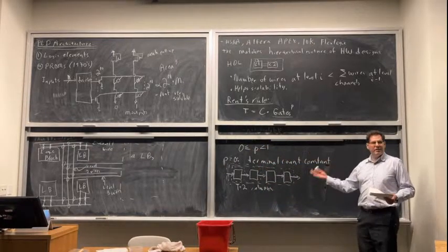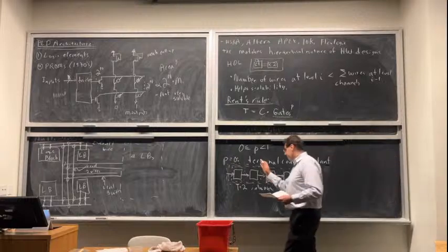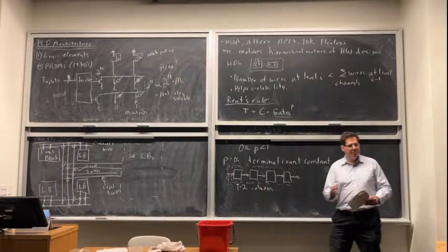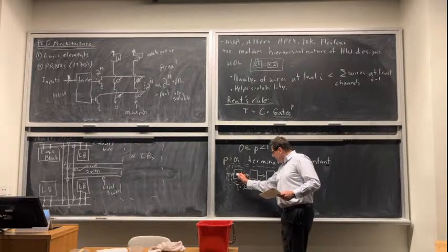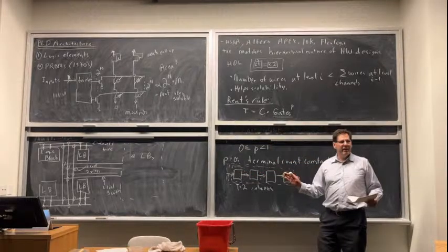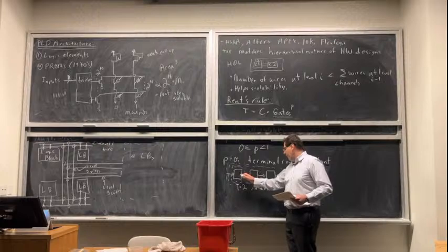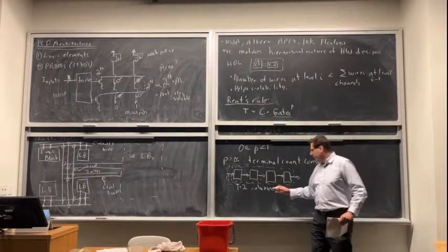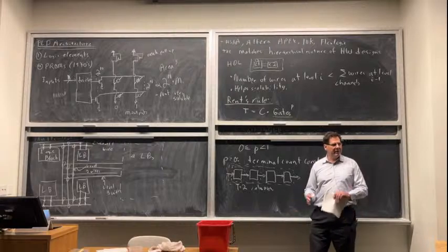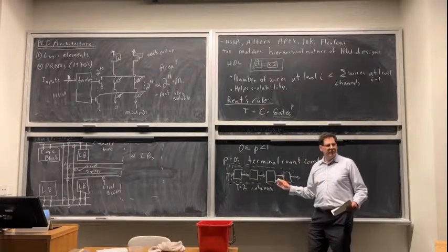And systems like this exist, right? Where you're just increasing the amount of computation, but in a linear pipeline. So your routing is very local. It also makes sense if you think of how far your wires have to go. They only have to go to the nearest neighbor. Your wires are all short. Your terminal count's not increasing. This would be a really nice circuit to lay out.